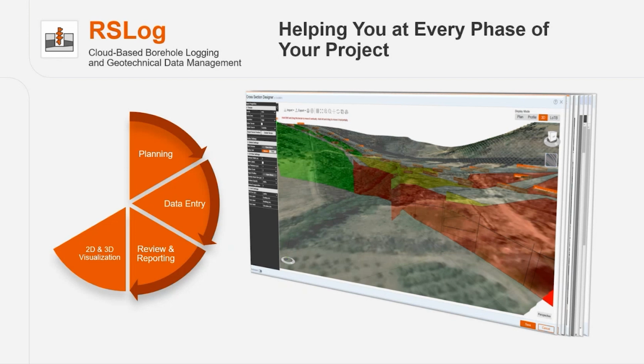For those of you who work with different DOTs in the US and you want to have the log of test boring, which is a summary of your boreholes in the construction drawings, we are working on a feature that exports the log of test boring for all of your project boreholes into DXF. So the only thing you need to do is to just open that DXF and copy the boreholes that you want with all their soil layers and test results and everything into your drawings.